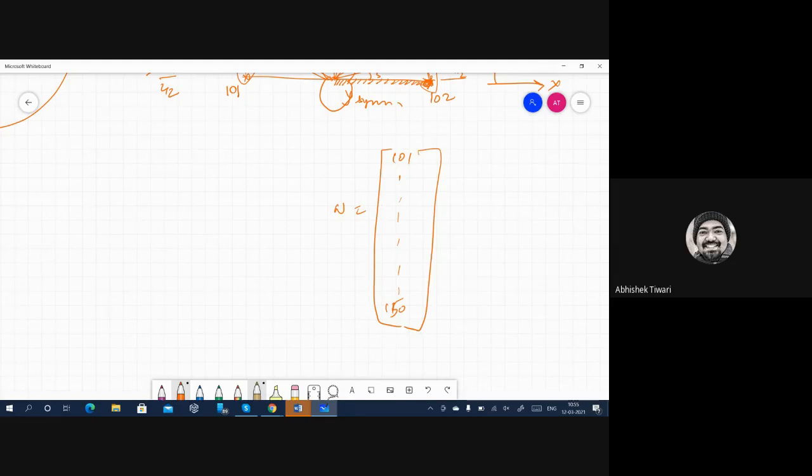See, hysteresis loop is actually two stress strain diagrams. One stress strain diagram in tension and another in compression. So if it is a tension-compression cycle, then you have a stress strain diagram in compression. So separate the upper part and plot it as a stress strain diagram, then draw a parallel line at 0.2% offset, and where it intersects, that will be your yield strength. So in one hysteresis loop you will get two yield strengths, one on the upper side, one on the lower side.